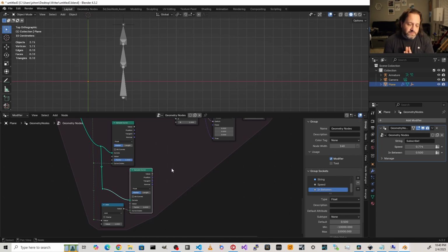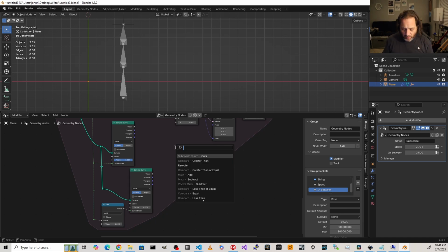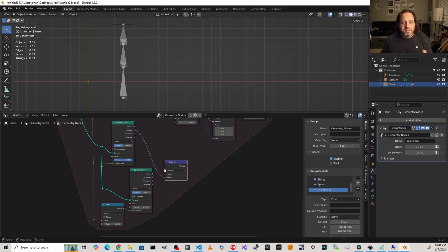Since these are both vectors, if we subtract the first one from the second one, what we're left with is a vector that represents the distance between these 2 points. So let's go ahead and do that with a vector math node. I'll take the second point and add a vector math subtract node and subtract the first point. So this is that vector, this is that line that you could consider drawing a line between the first point and the second point, and then just taking that line and moving it down so that the beginning of the line is at the origin.